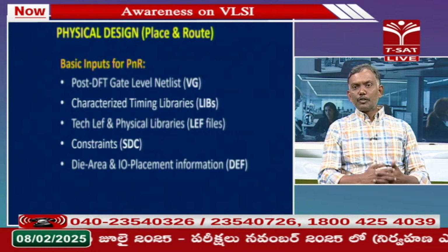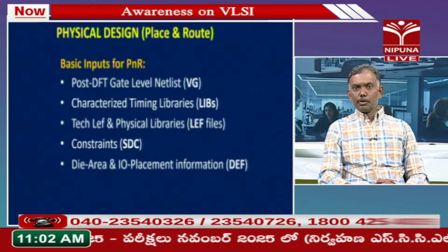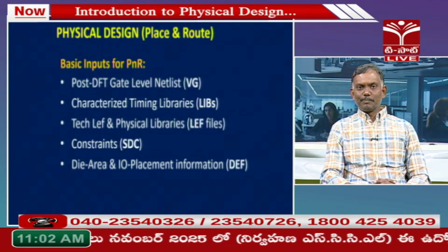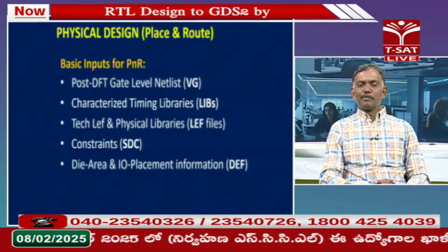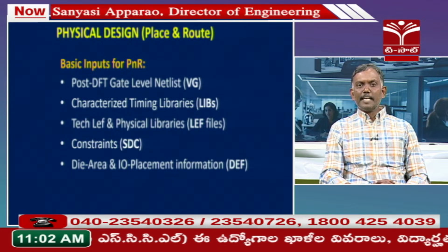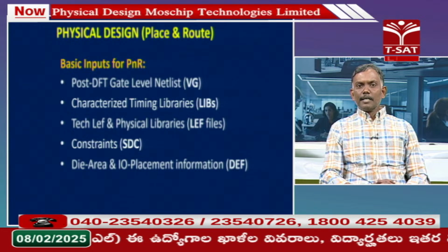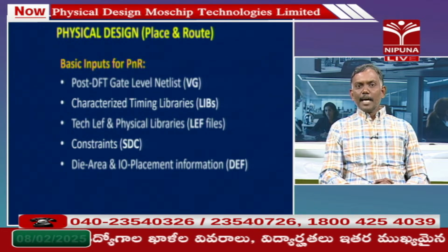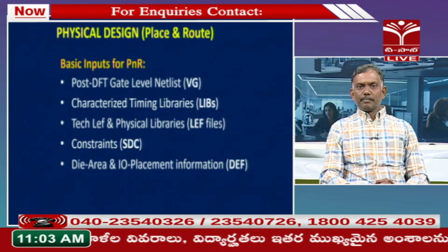We should read that information also, because it is place and route, and we are doing the routing, right. We need all the layer information for the delay and for completion of routing, and macro LEFs.